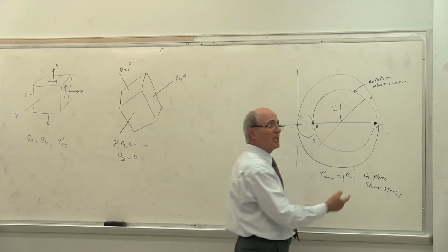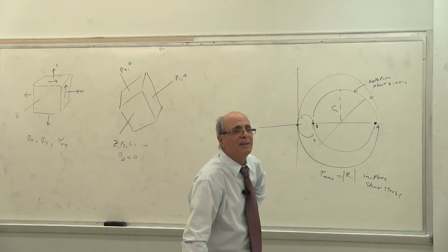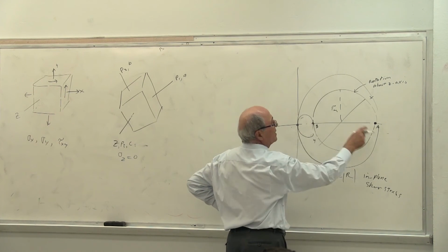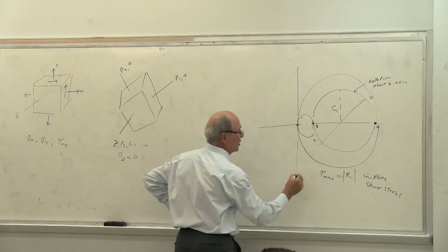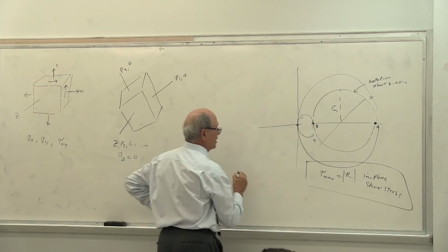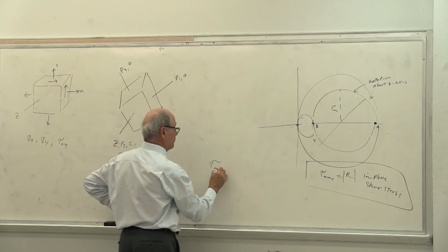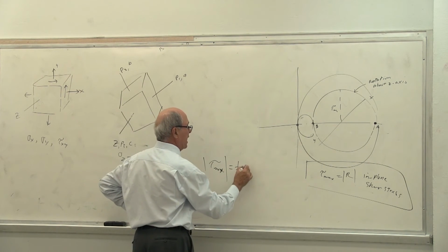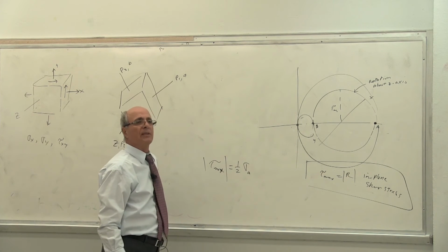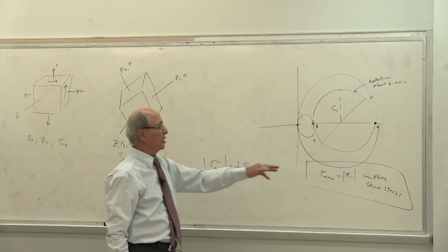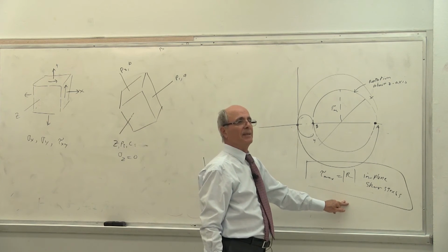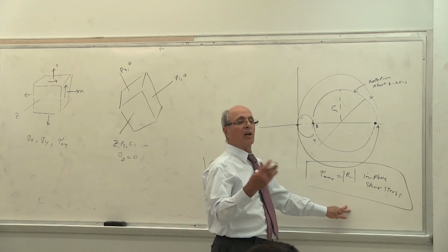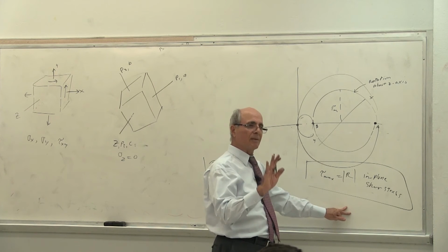Which one of these three circles has the maximum shear? X and Z. How much is that? Tau max, write it down. This was in-plane shear. The tau max here, for this problem that you saw, is equal to 1/2 of sigma A. Yes or no? Yes? Which is much larger than this one. Correct? Now this is only a larger circle when, yes, there are different options.